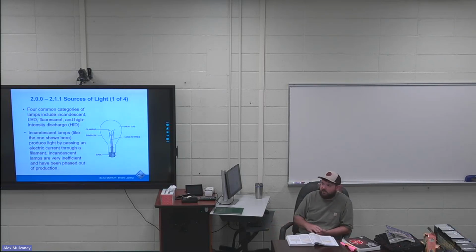If you ever see the newer street lights that they're putting in, or even if you're in a night class here at Nunez, right now there's a light out back. It's one of Entergy's LED lights, and it just sits there and flashes and flashes. That's a telltale sign of a bad LED driver.